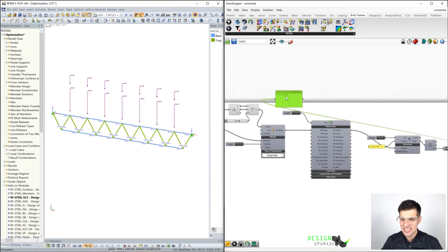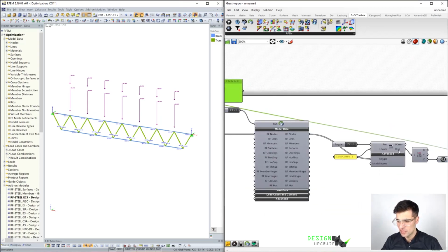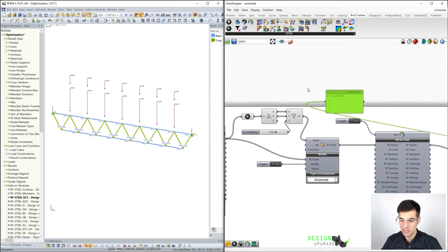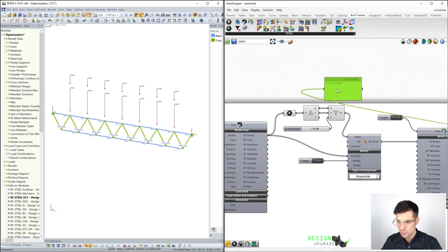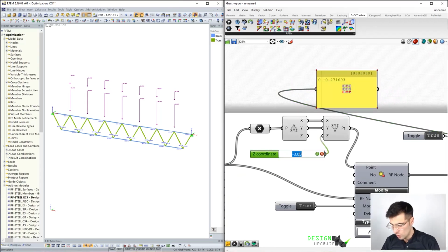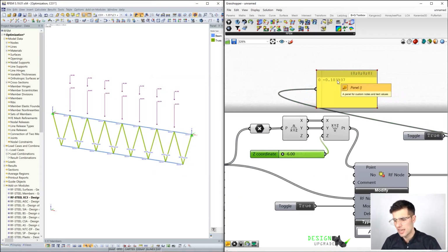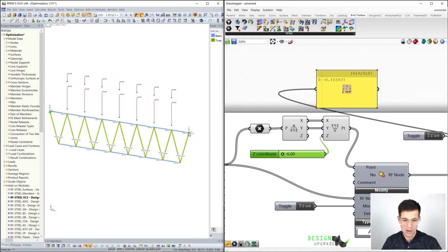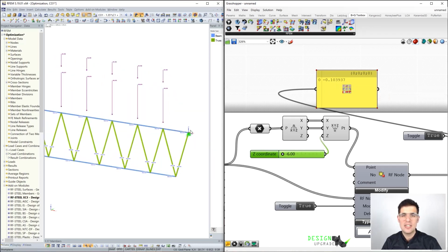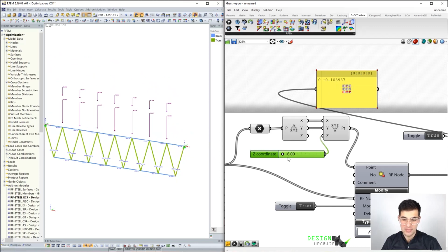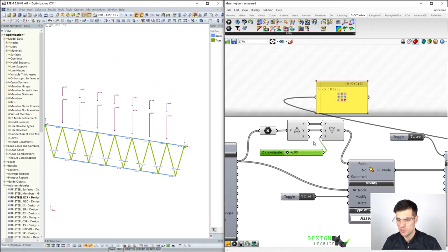So this is in this case 0.2, this would be meters, so 30 centimeters, okay, not bad. And we can see, for instance, when we do this, instead of -3, -6, how the deformation is much lower now, just 10 centimeters. And yeah, of course, because the upper chord is located in the coordinate 0, C0, so we are specifying basically the truss height with this parameter.